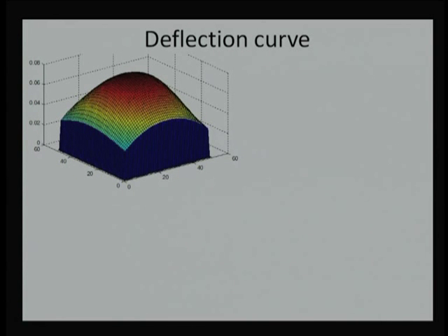From those pressures, find out the deformation at every node, and redo it. You can come back, calculate the film thickness at every node, and use that film thickness expression to find the hydrodynamic pressure. From the hydrodynamic pressure, again find out the deflection, and it needs to go through a number of iterations to find the final converged solution.